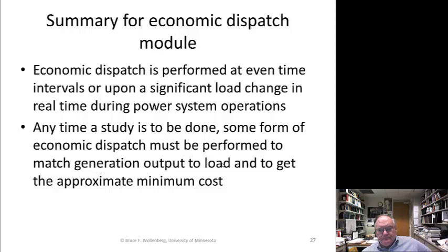Okay, let's just do a little summary. Economic dispatch is performed at even time intervals, or upon a significant load change in real time when we're studying. So it's very important as you're operating the system to keep doing economic dispatch to keep the system operating at the lowest cost.